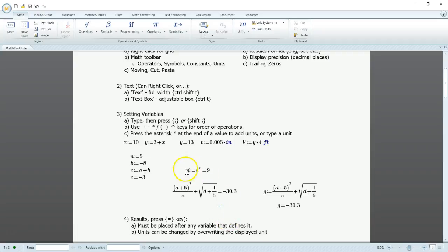Now here's a good time to mention a few things. The power of Mathcad is that all these expressions, or all my inputs, are variables and I can change them. So from 5, maybe I wanted 15. And you can see that everything was updated. One more thing is the equations must come after variables. I cannot put C above A and B. When I do, we realize that B is undefined because it comes after, and that works left to right, top to bottom.